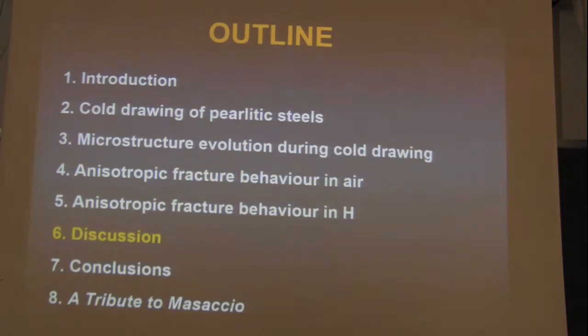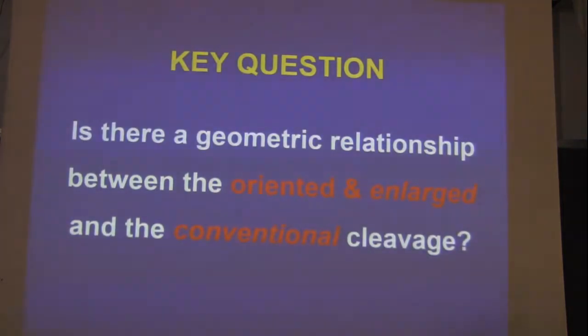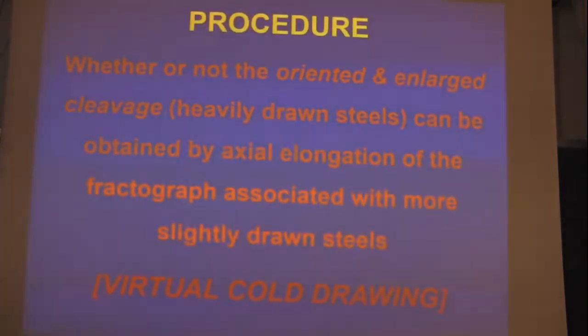Now a discussion regarding fracture in air. We leave the hydrogen-assisted fracture, hydrogen-assisted cracking, and we formulate a basic question for fracture in air. Key question: is there a geometric relationship between the oriented and enlarged cleavage and the conventional cleavage? The idea comes from the hydrogen damage topographies, which are virtually drawn in the computer to obtain the same appearance.